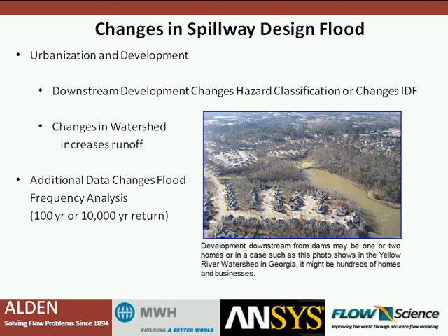Our flood frequency analysis has also changed over time. In the intervening years since these projects were built, we've been able to collect a lot more stream flow data. So what might have been designed for 30 years of data, we might now have 60 or 70 years of data. And when you do that, that can actually change the magnitude of the design flood if you're calculating a 100-year flood or even a 10,000-year flood.